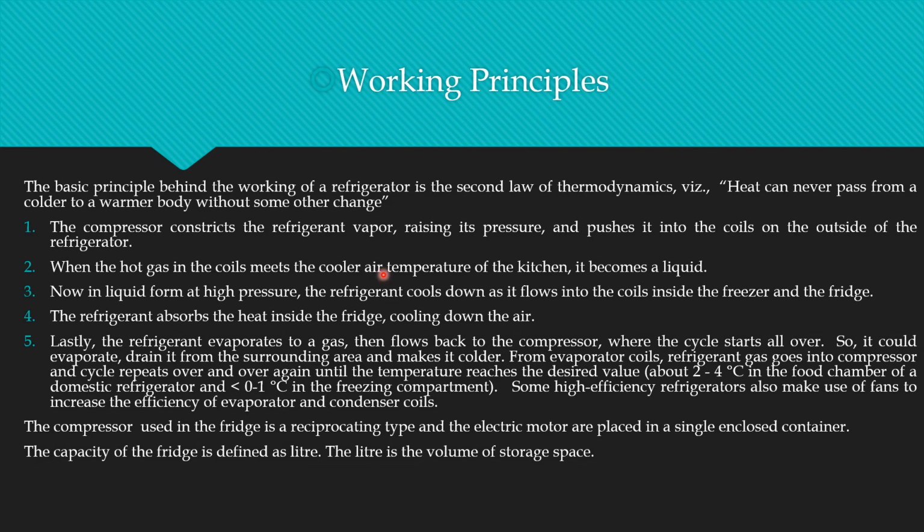That is the condenser, which means it will change phase. Freon gas becomes freon liquid. Now the liquid freon enters the capillary tube or expansion valve. Liquid from the high pressure refrigerant flows into the coil through the expansion tube or capillary tube. Then it will expand and reduce the temperature further.